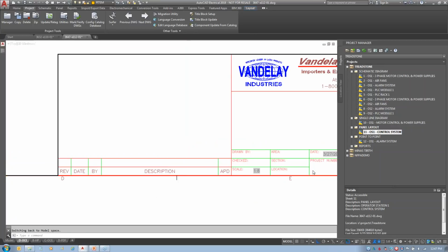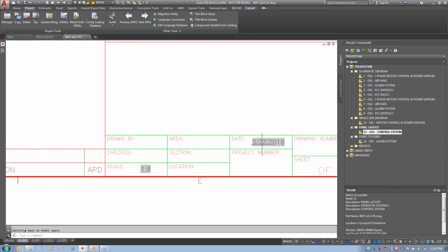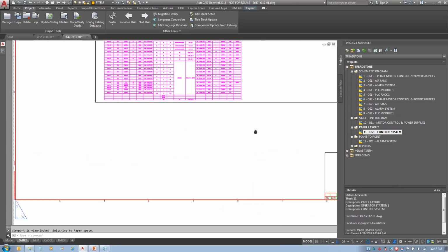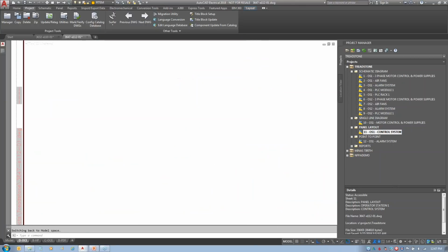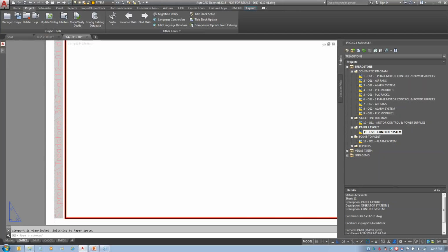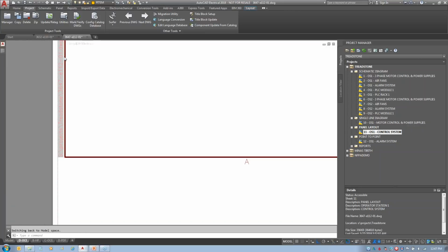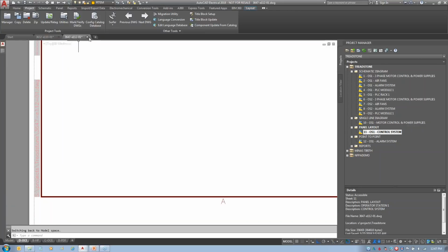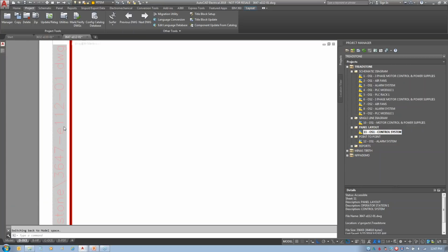The date is just connected to, I have it connected to the date of when you hit create new drawing. So it puts that date in there and that becomes the date. So fields are pulling document information or object information into it. So you can see here it's pulling the file name. If I did a save as another file name, right now it's E112-001.